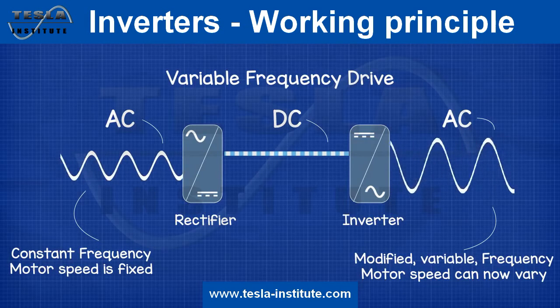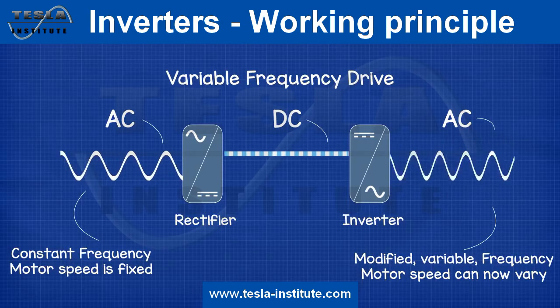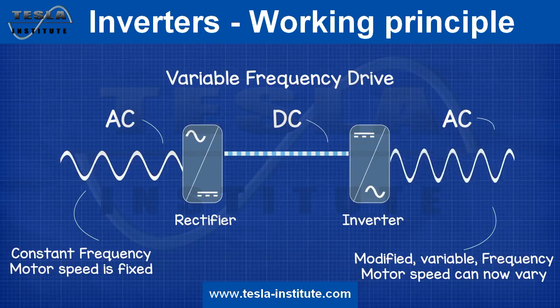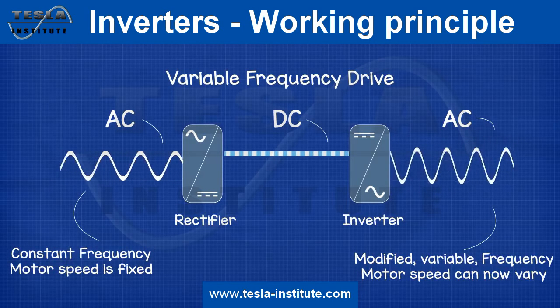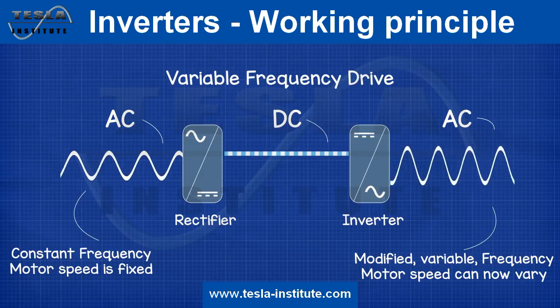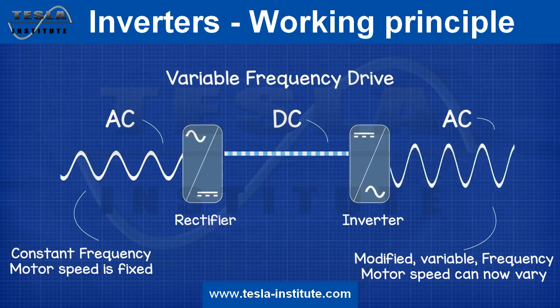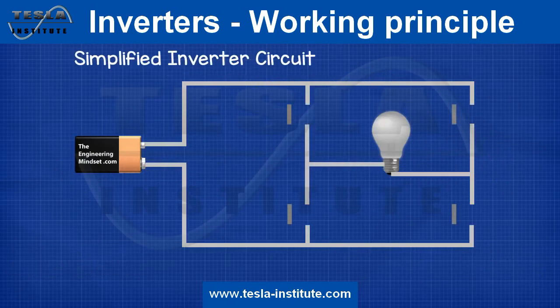It has a very clever control loop which is measuring the cooling load and then changes the speed of the motor, which changes the speed of the scroll compressor, and that increases or decreases the cooling capacity to match the load, which results in precise temperature control as well as energy savings. So how do they work?